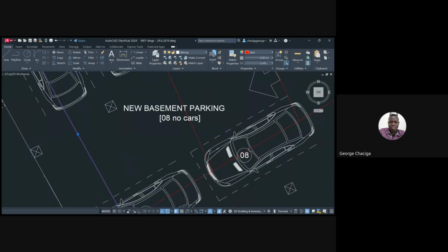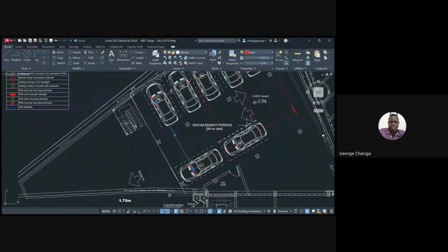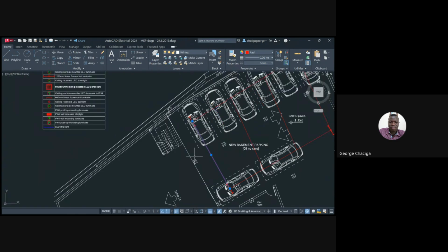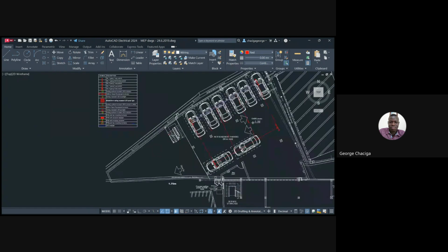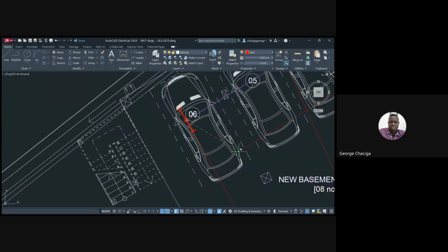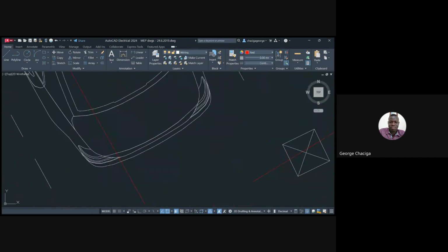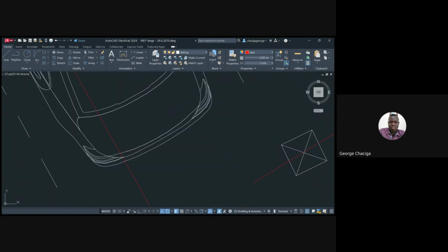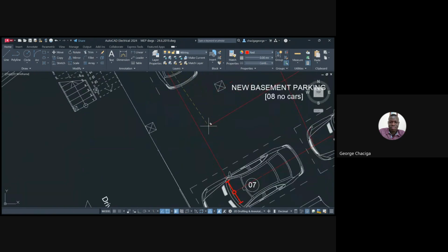Here we use the divide thing. Why? Because if you put it in the center, the distance will still be greater than the 4.5 that we are targeting. So what we do here, since they've seen dividing the line into 2 points, just come select this at its endpoint and bring it to the midpoint.